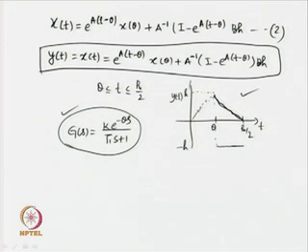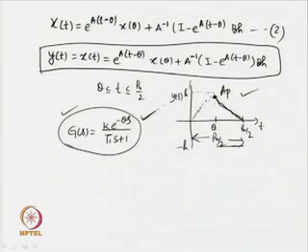So, the measurements made on the output, what measurements can we make? We can measure the peak amplitude of this output. Also, we can measure the half period of the output using zero crossing detectors. So, when the measurements are made and when the expressions are found to involve those measured quantities, then it is not difficult to solve the analytical expressions and find the unknowns associated with the transfer function model.